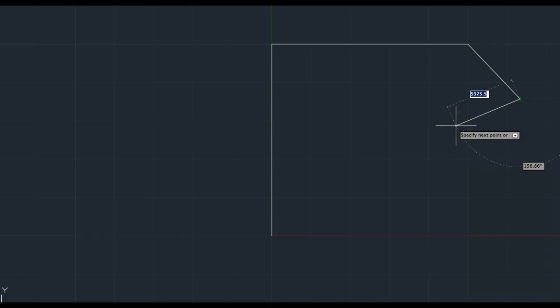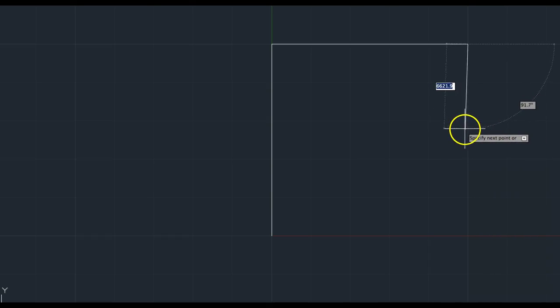The next line we are creating is the second vertical one. This is different to the first line we drew, as it goes down the screen rather than up. To do this, we make the y value negative. Type in 0 for the x-axis. Remember we are drawing a vertical line. Then type in minus 10,000 for y. The command should be 0 minus 10,000. Press enter to finish the line.